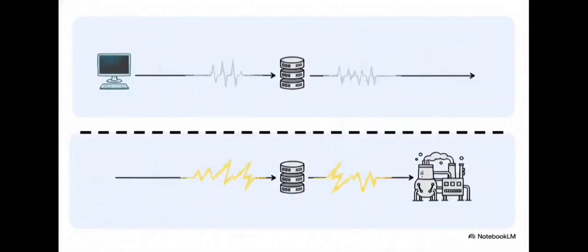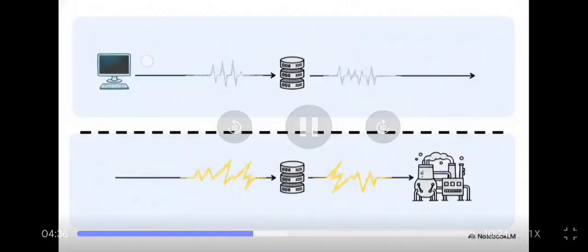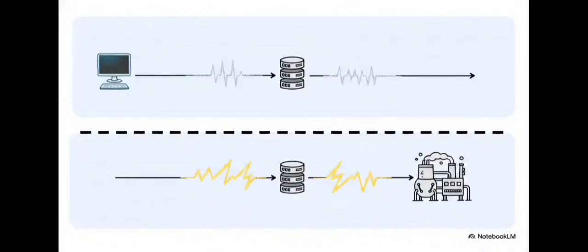Now, connecting these big brains to the human operators requires incredibly disciplined traffic management. Industrial Ethernet solves this by cleanly separating the traffic into 2 distinct highways. You've got the terminal bus, which connects the operator clients to the servers using standard TCP/IP traffic, but underneath that, strictly separated, is the plant bus, linking the servers down to the raw automation systems. Keeping these two completely isolated ensures that someone running a heavy database query in the control room doesn't accidentally jam up the real-time commands that are keeping a high-pressure reactor stable.